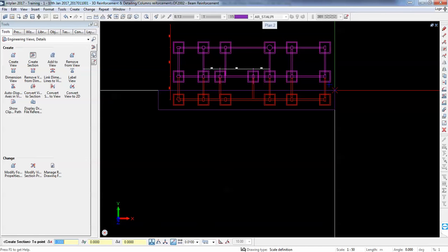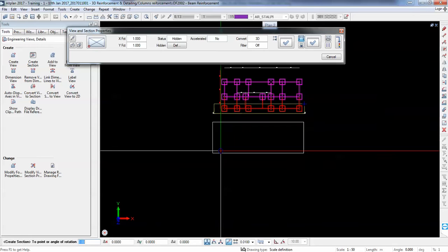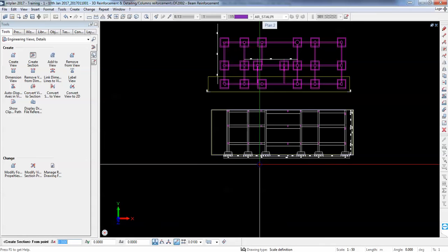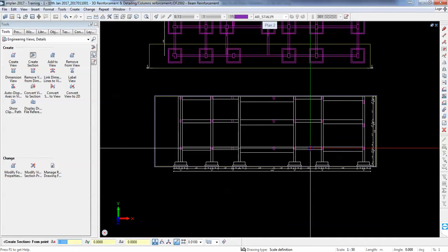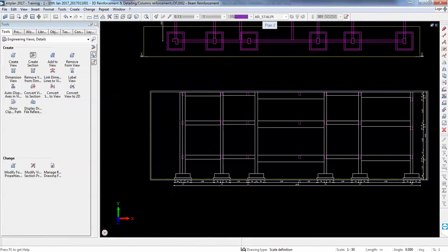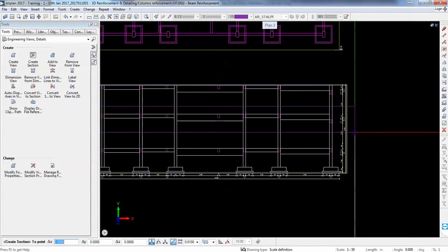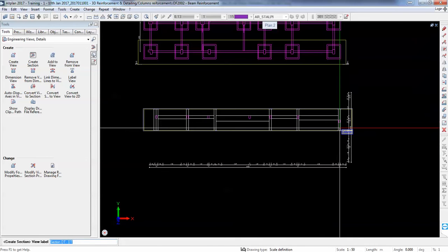So I do 2 clicks diagonally, then I hit escape. Then I place the result, and without doing anything from this point, it asks here from point. So without hitting escape or any other button, I can choose the beams that I like. So I'm creating now another polygon like this. One click here, and the other to define the diagonal of a rectangle that will contain what I detailed. And then escape. So this is how I do it.